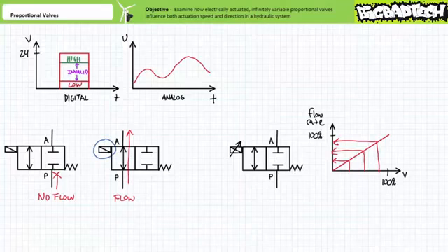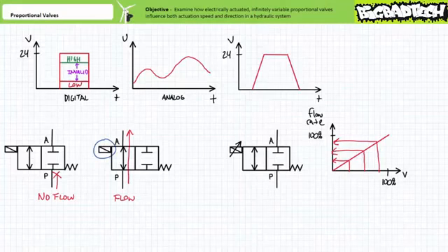While substantially more expensive than a regular flow control valve and directional control valve combination, a proportional valve offers additional functionality in a single package. In addition to simultaneously controlling actuator speed and direction, being analog in nature, the pressure shock associated with a traditional fully closed or fully open directional control valve can be mitigated in that applied voltage can be smoothly ramped up over time, thereby slowly opening the valve and suppressing the shock. This ramping event controls the acceleration and deceleration of the applied load, as we'll learn in a moment.